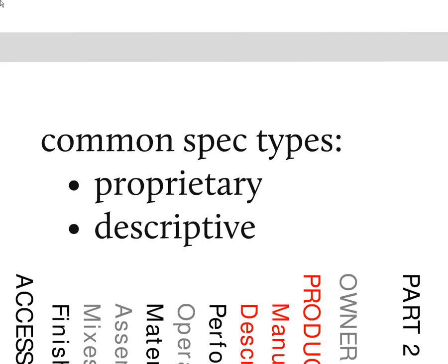Yes, and to help fend off unnecessary and annoying substitution requests, even if I'm going to name names and model numbers, I usually find it very effective to have a brief description of what the product is and its salient features, to fend off the folks that may have a similar product but don't have all of the qualities that I need for this particular project.